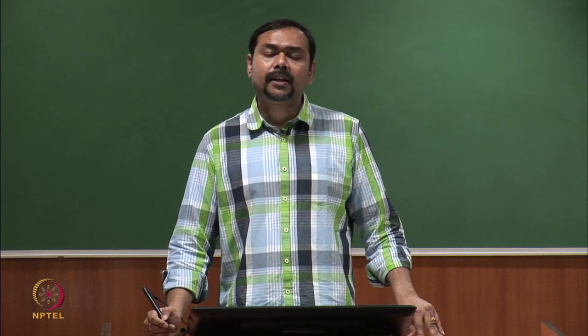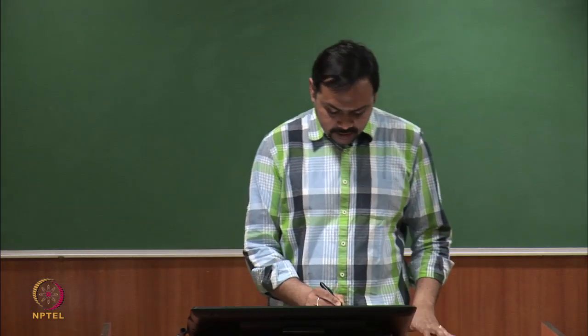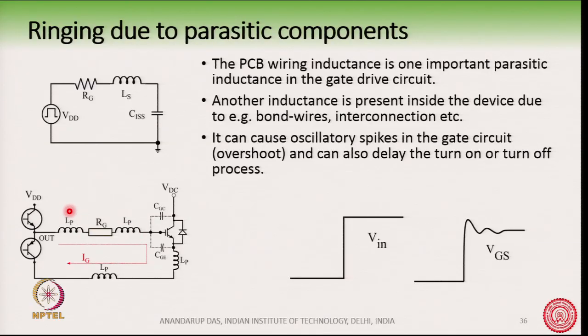So, we would definitely want to make this distance small. Here it is shown, this LP, these are part of the PCB wiring inductances. So, these should be minimized as much as possible.